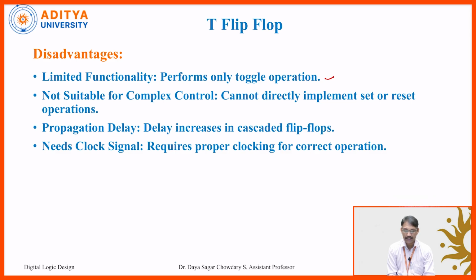It cannot directly implement set or reset operation because only one input is there. If we apply 1, both inputs get 1. If we apply 0, both J and K inputs get 0. That is why we cannot give the set and reset conditions.